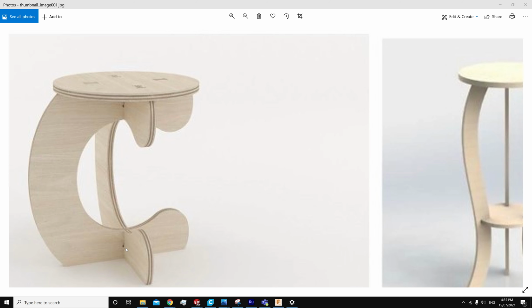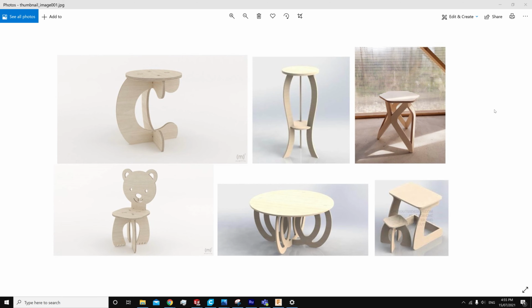That's not always necessary. If you're trying to produce things in quantity to send out to a customer, then it probably would be necessary to do that. If you're producing something for yourself, then that isn't really necessary, because you can easily get a chisel or a file and get rid of that bit yourself. The advantage of doing it yourself is that you don't have to worry about that dog bone being visible. In fact, another thing you could do, if you've got two parts slotting together, is simply round over one of the parts to give it that radius. So you could keep those nice rounded corners within that slot. So those are two examples.